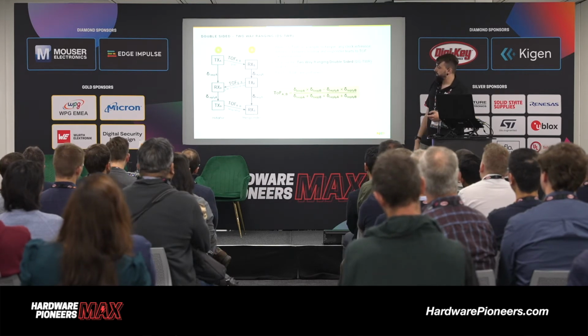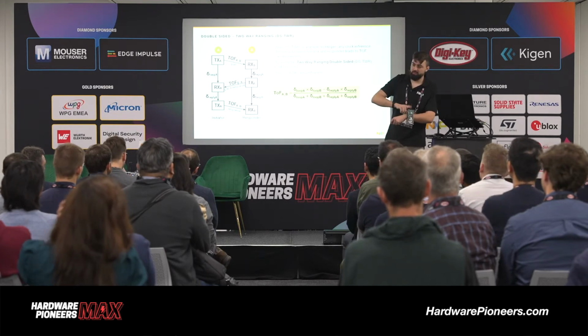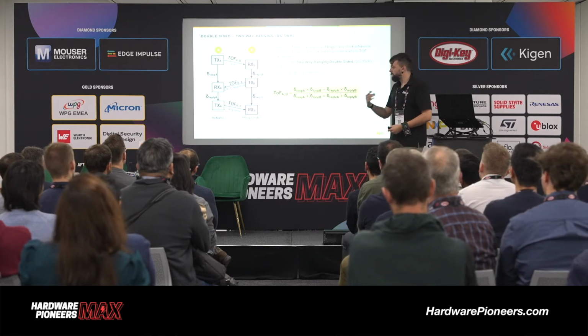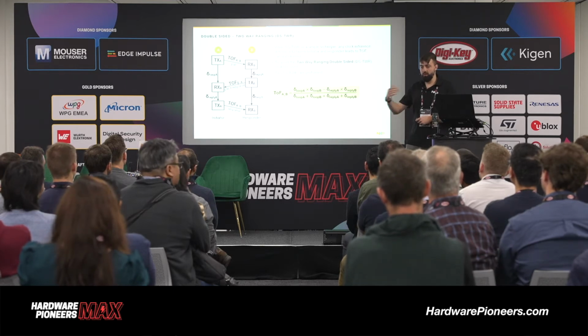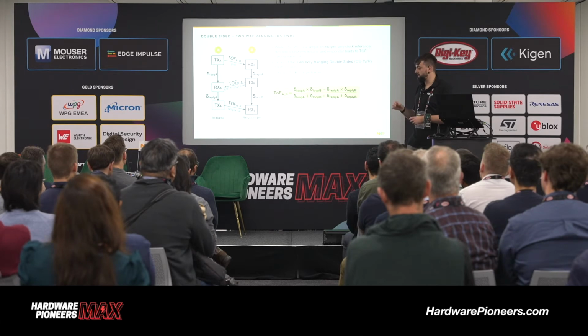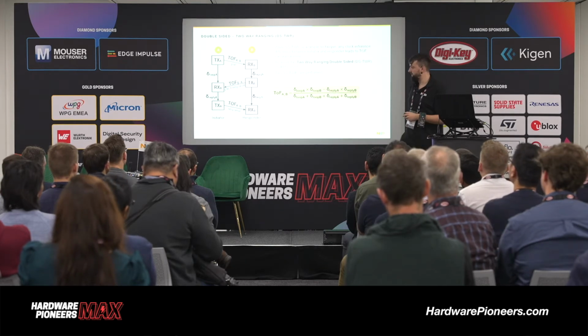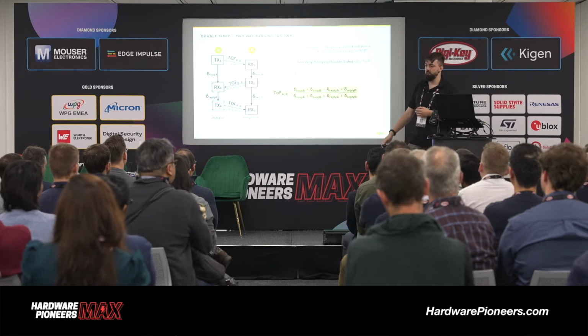To improve on that, we can also do double-sided two-way ranging. After we have one ranging round, we again send one signal to the partner device and receive one signal back. This improves the ranging technique by reducing the clock error on one device. So one clock is cancelled out by the equation, which you can see here. It's a little bit complicated, but it's not that hard. In the end, it's the same again. You do it twice to improve the accuracy, and we can go down to plus minus 5 centimeters in ranging accuracy.